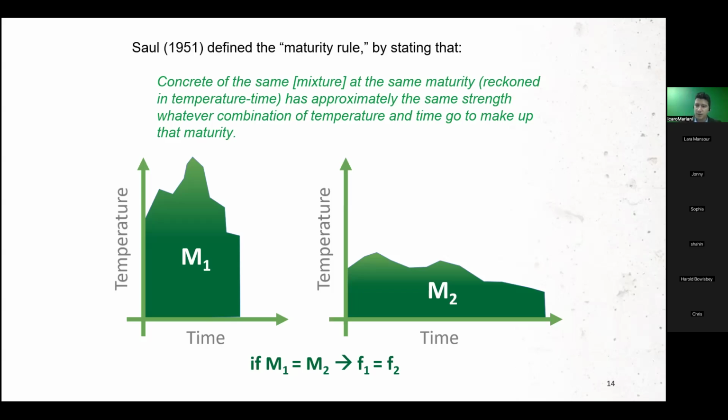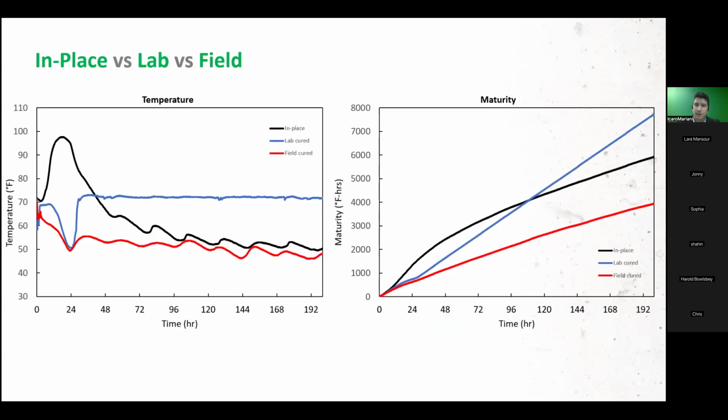So that's one of the goals, and having an integrated system allows you to have the sensors, have a modem. That modem connects to the sensors. We call it Smart Hub, and it triggers push notifications 24/7 to users, letting them know, okay, your temperature is too low. Go back to the job site and turn on your heaters, put blankets, or take proactive measures before you run into a non-conformity.